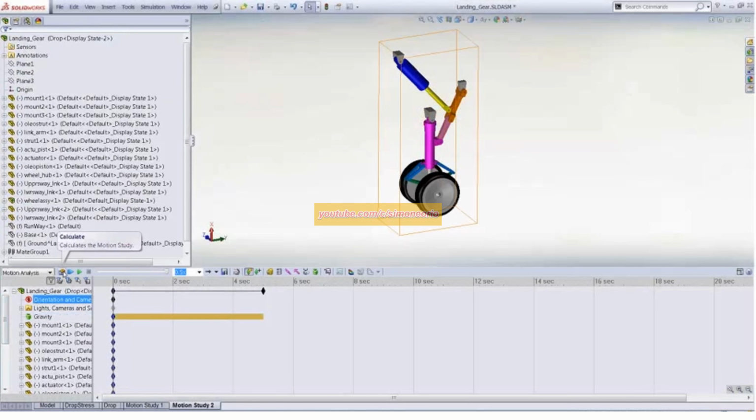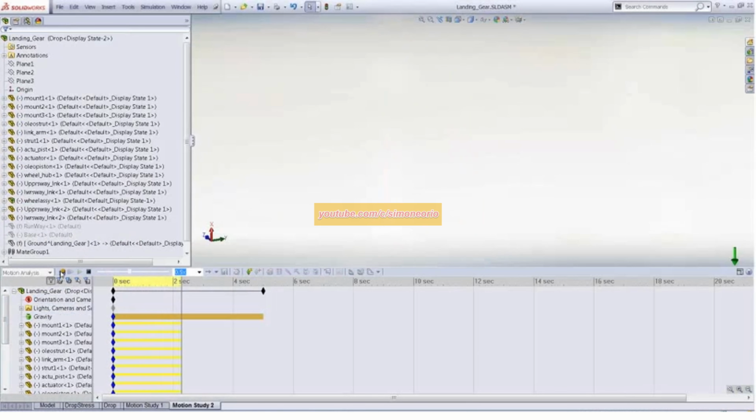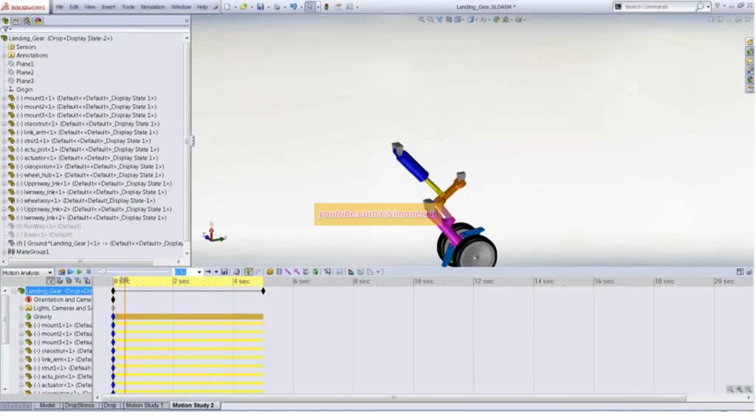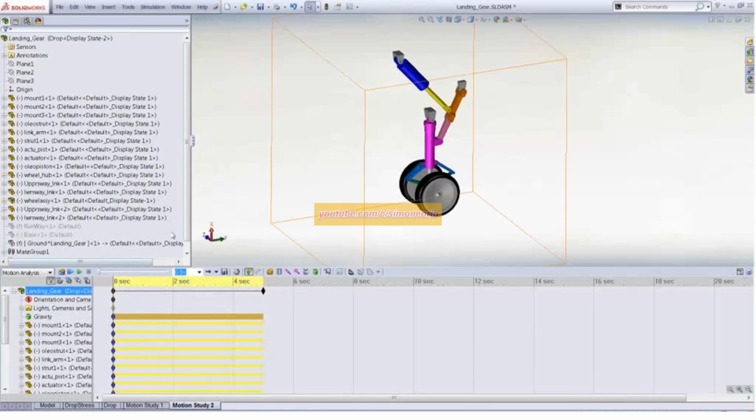Now the palette turns colorful here with the calculation button because we have something to solve. Right now, there's not much to solve other than our landing gear is dropping like a rock. We do see that kinematic relationships between our parts have already been predefined with our motion mates. So now I can start using things like motors to begin constraining the model and adding forces.